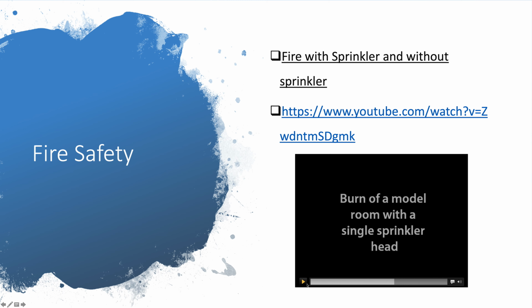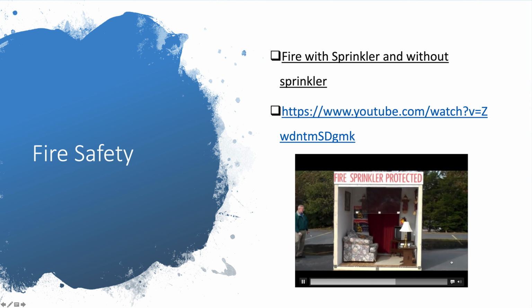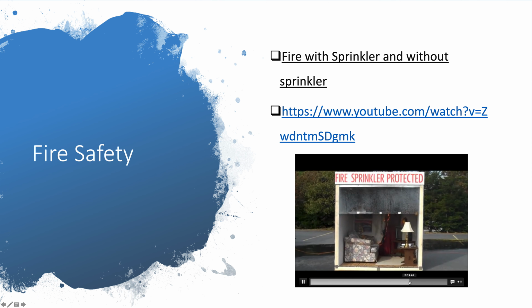It's still going to travel up the curtain. The sprinkler needs to see 155 degrees, the ceiling temperature, and the smoke alarm goes off. You see the fire occurs, we have activation, and the sprinkler is activated now. The activation happens in about 20 seconds. Yes, you can see it happens in 20 seconds.